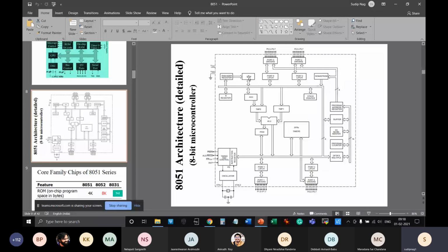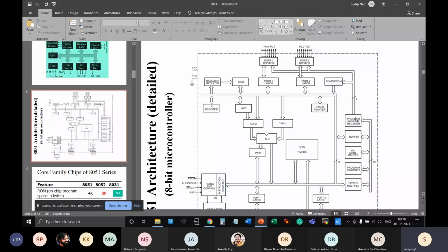So in this instance, MOVX A, @R0, basically the value of R0 is coming over here, going through the data bus and then going through the buffer. The buffer is nothing but the same connection, just to prevent extra hardware loading, meaning extra capacitive loading. Whatever R0's value is, it comes and sits over here in the program address register. From the program address register, it's an 8-bit address.